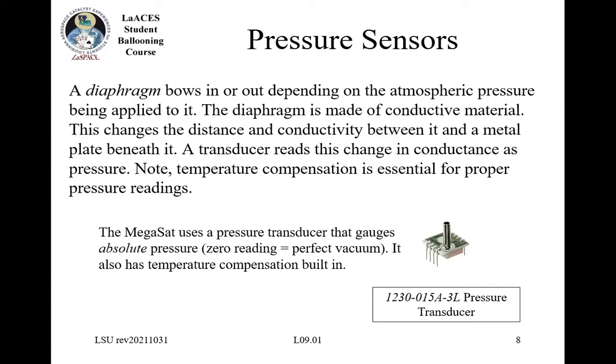Inside of this device, there's basically a section that has a vacuum in it. So it's going to measure the difference between the ambient pressure and that vacuum. You can see that there's actually another little circle here. So there are versions of this thing that basically have two tubes coming out of it. And what it will measure is the pressure difference of whatever's in those two tubes.